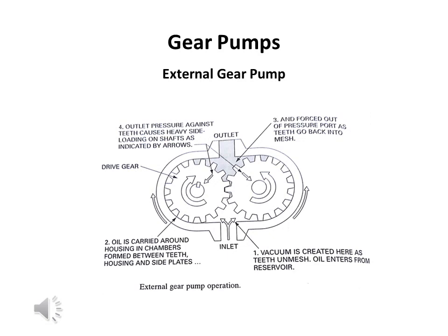When it is moving into the top of the pump, there will be a restriction, and pressure will develop. The pressure will gradually mount on the top of the pump. Once it reaches the required level, the discharge valve will automatically open, and the high pressure oil will get into the fluid power circuit. So this is the working of the external gear pump.